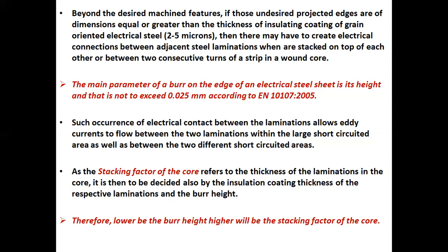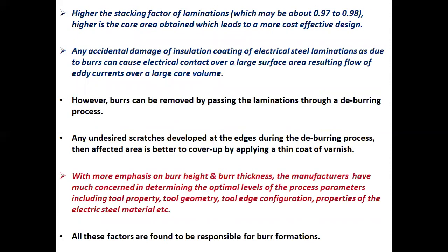As the stacking factor of the core refers to the thickness of the laminations in the core, it is to be decided also by the insulation coating thickness of the respective laminations and the burr height. Therefore, the lower the burr height, the higher will be the stacking factor of the core. The higher the stacking factor of laminations, which may be about 0.97 to 0.98, the higher is the core area obtained, which leads to a more cost-effective design.